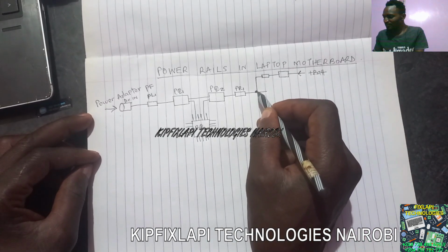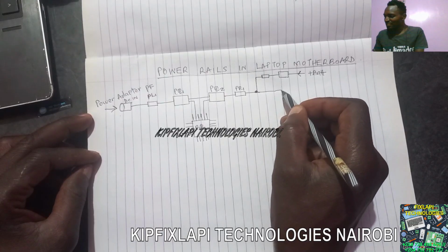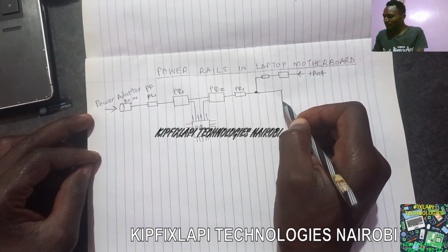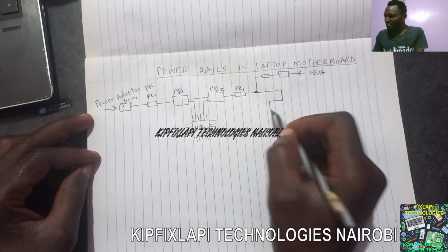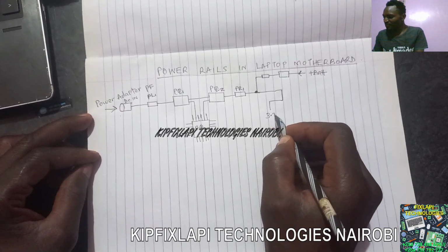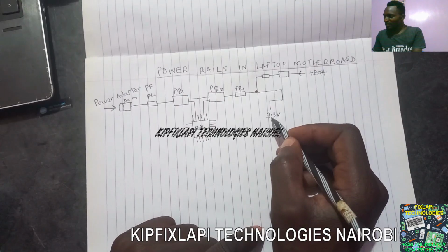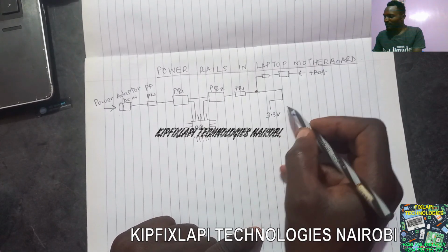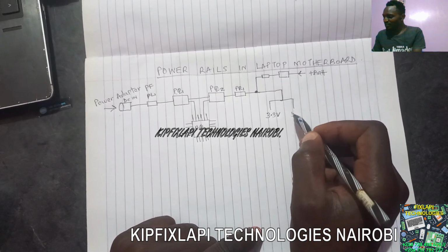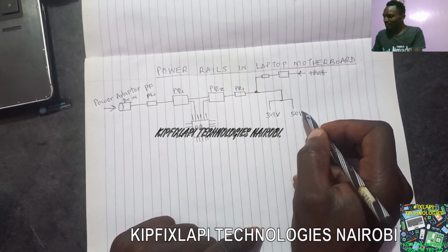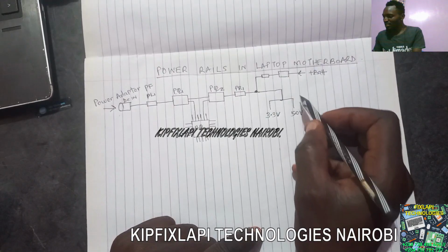So they join here. Once they join, they proceed into the motherboard, and at the first branch of the power supply, we will have a circuit which generates 3.3 voltage, and this 3.3 voltage supplies the SIO. It also supplies the processor. And then you have another voltage out of this circuit, which is 5.0 voltage. This 5.0 voltage supplies the south bridge of the PCH.